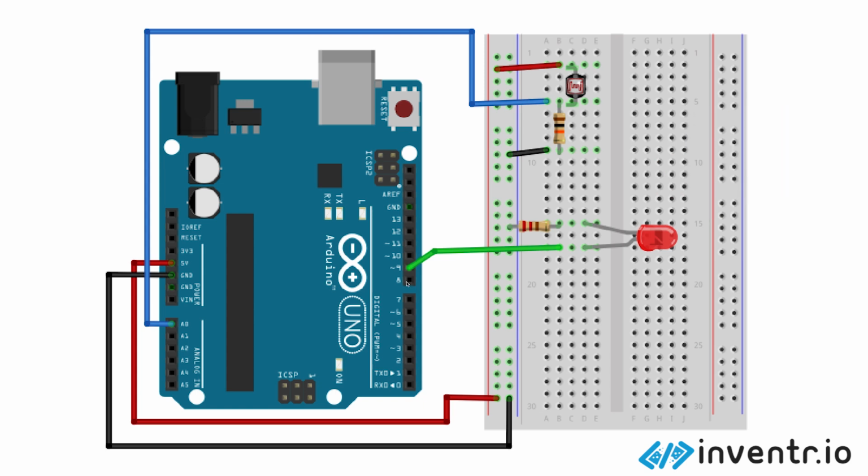If you put it on 8, we would not have that available to us simply because it's not pulse width modulation, so you can't change what voltage is on this line. It's either the voltage that's going out or there is no voltage going out. This one, you can set it to a certain value, or there's a certain range of values that it can be put to. Other than that, this is basically how you'd wire it up.